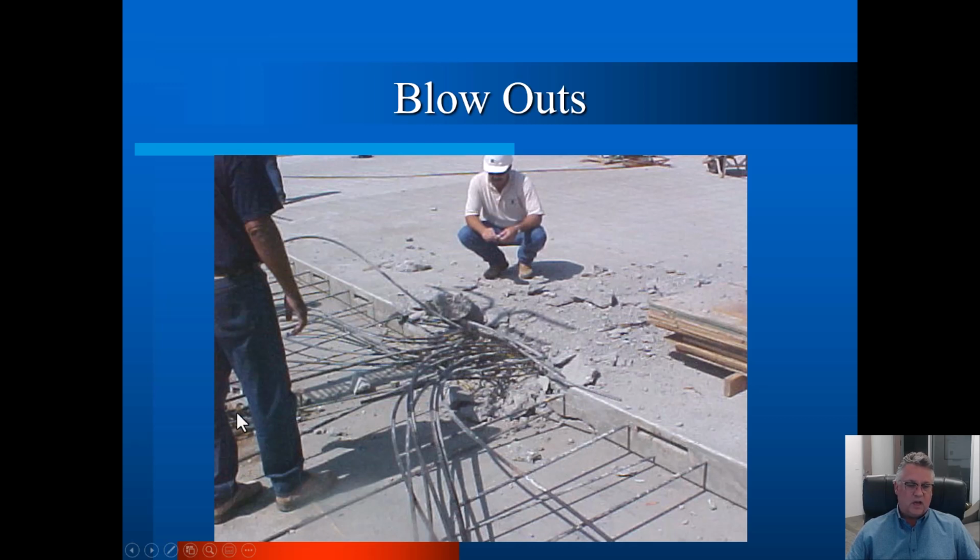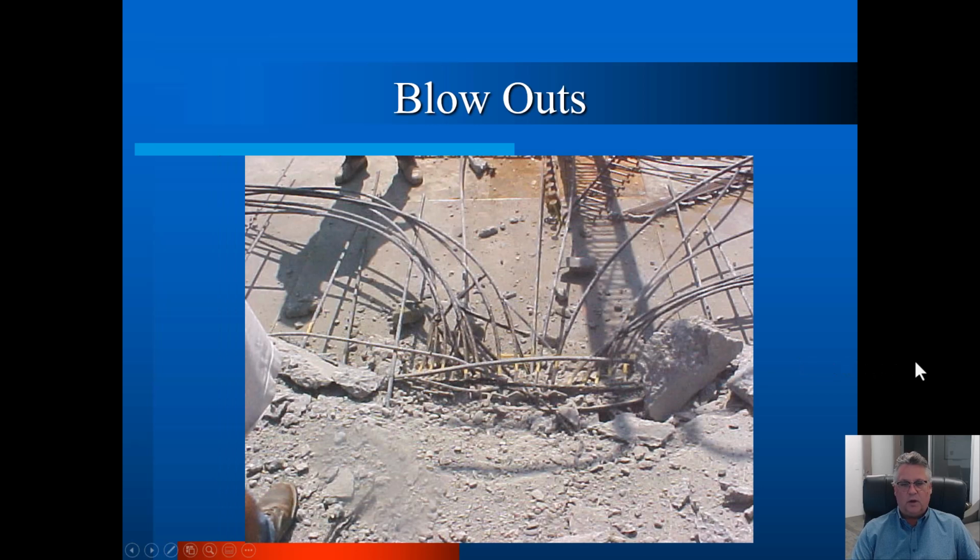And I think in the next slide you'll see that the confinement reinforcement of stud rails was actually just sitting over here. It was supposed to go in. You kind of see them just laying over here. Nobody decided to put them actually in the slab that needed it. This was probably 3,500 psi concrete that became dust. Pieces of concrete flew about 40 feet.